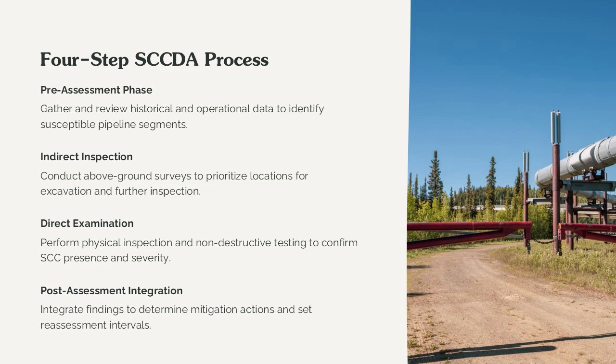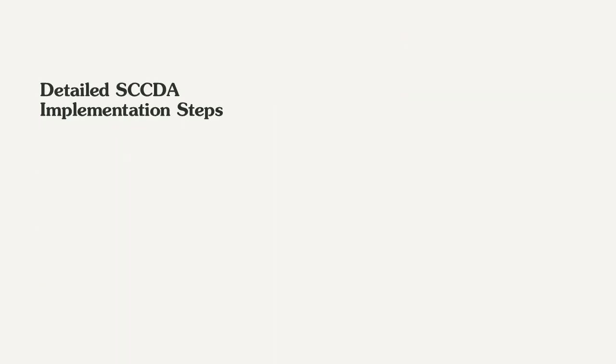Direct examination confirms the presence and severity of SCC through physical inspection and non-destructive testing. Finally, post-assessment integrates all findings to determine mitigation actions and establish reassessment intervals. This structured approach ensures consistency, traceability, and defensibility of integrity decisions, which is especially important for regulatory compliance and risk management. Detailed SCCDA implementation steps: pre-assessment, indirect inspection, direct examination, post-assessment.